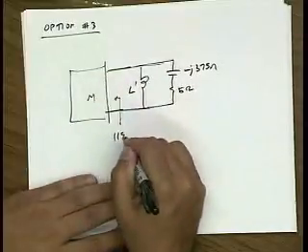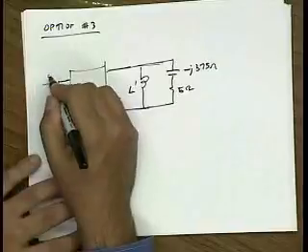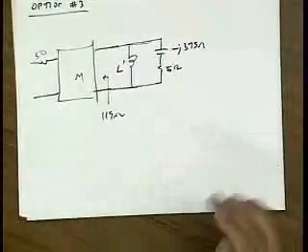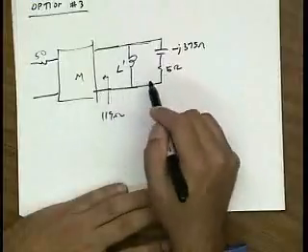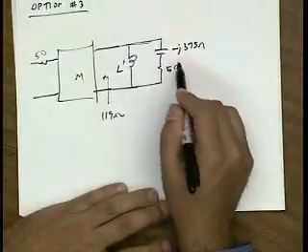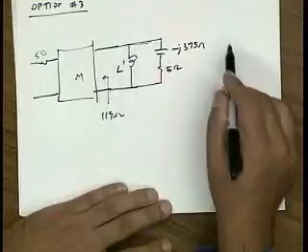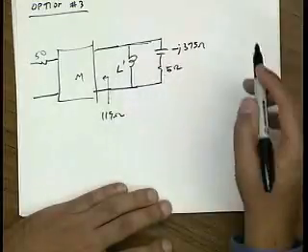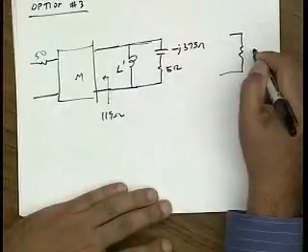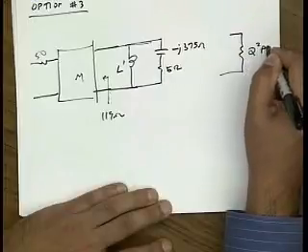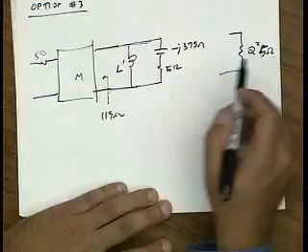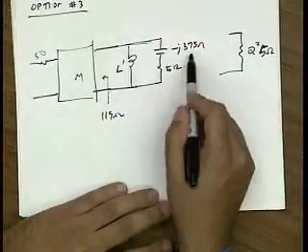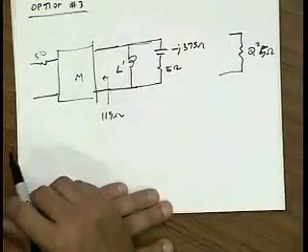I still have 119 ohms here, and this is in the 50 ohm system. Well, remember, if I put an inductor in shunt here, I can do a series to parallel transformation. So the equivalent parallel resistance seen here in resonance just looks like Q squared times 5 ohms, right? So the question is, what's the Q? The Q is just simply 375 divided by 5.